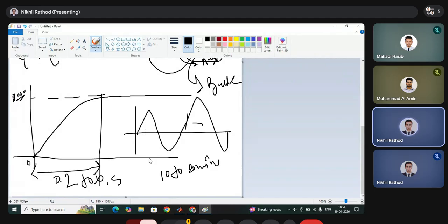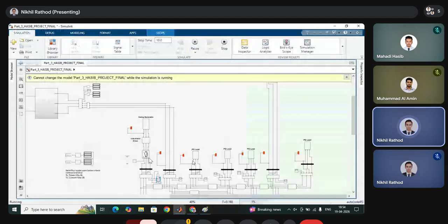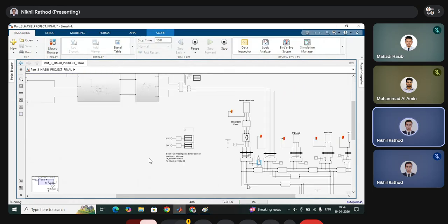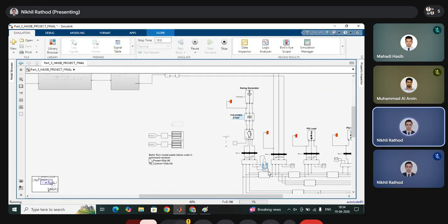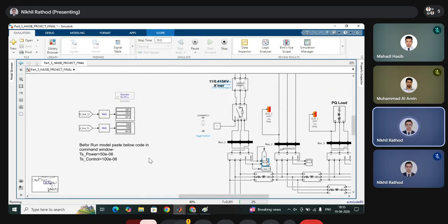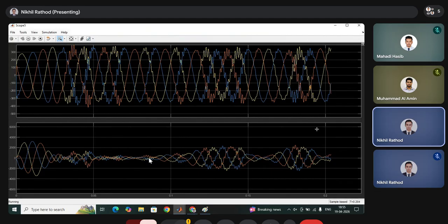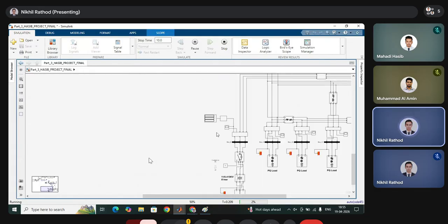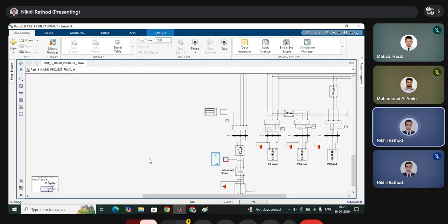If any type of abnormality comes or any switching happens, a slight variation in the sine wave causes instability in this VSC controller, and that eventually causes disturbance. You can see the disturbance coming after the turning on and off. It will stabilize after some time, but yes, it is coming due to the instability. Let's just turn on the breaker again.